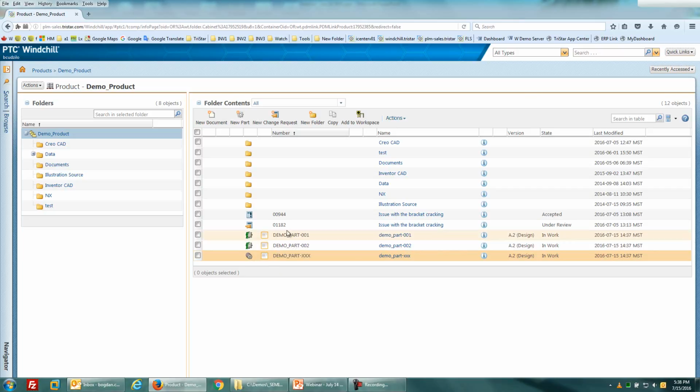How do you generate these through CAD software? Really, you won't be able to directly until Windchill 11, because in Windchill 11 you can pick the WT part subtype that gets created as you check in a CAD model. But you can create these and then associate them afterwards if you need to, to the same CAD model that the generic owner is referencing, or the family owner is referencing.